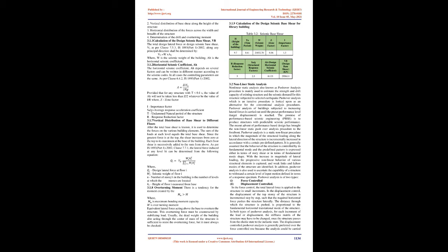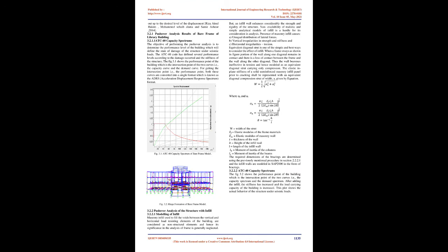In elastic analysis, the stiffness characteristics of the structure are assumed to be constant for the whole duration of the earthquake. In the inelastic analysis, the stiffness is assumed to be constant through the incremental time only. 2. Description of structure. In this report, a RC-framed building was taken for analysis, G+2. The RC frame model is subjected to an earthquake located in seismic zone V. In the above model, the support condition was assumed to be fixed and the soil condition was assumed as medium soil.